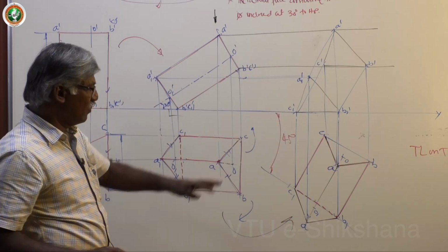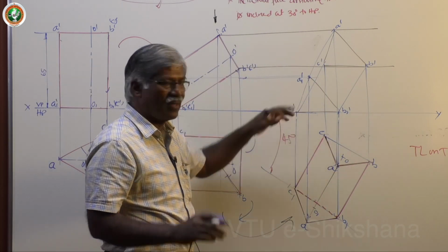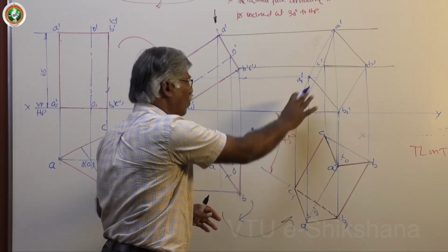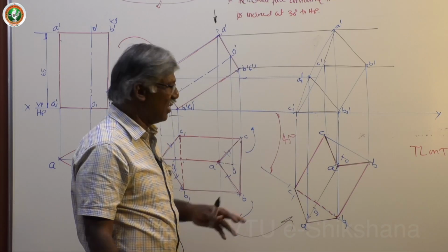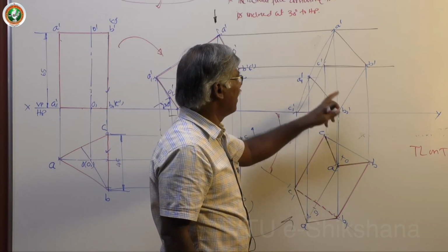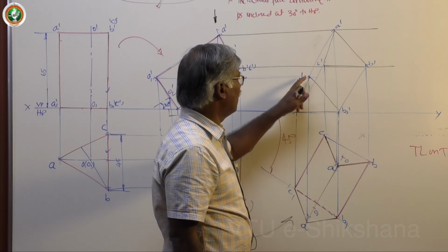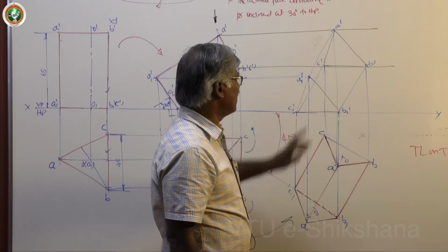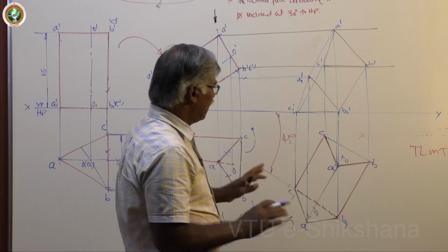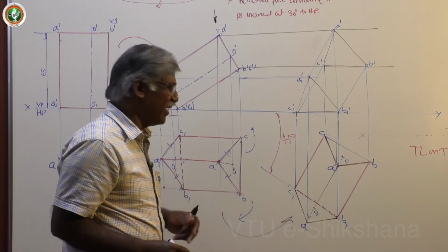Three stages. First, project onto the base. In computer you can use alignment indicator, do only that. I will show you how to do it. Again you project it and get that. Then join the respective corners. Easy. AA1, BB1, CC1. Now, axis also you can do at the end.